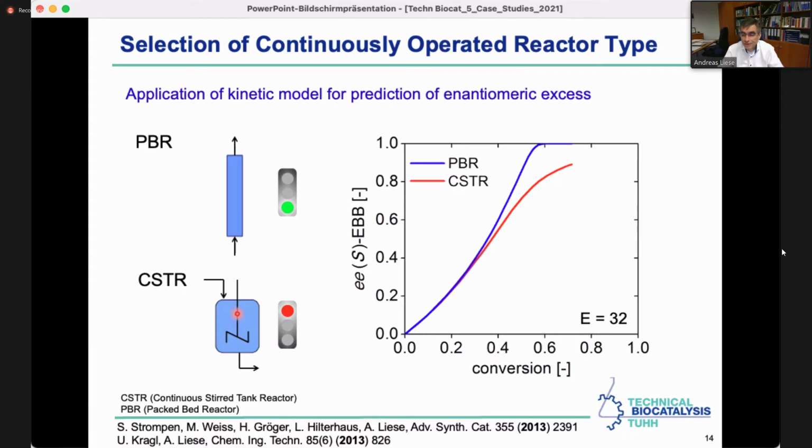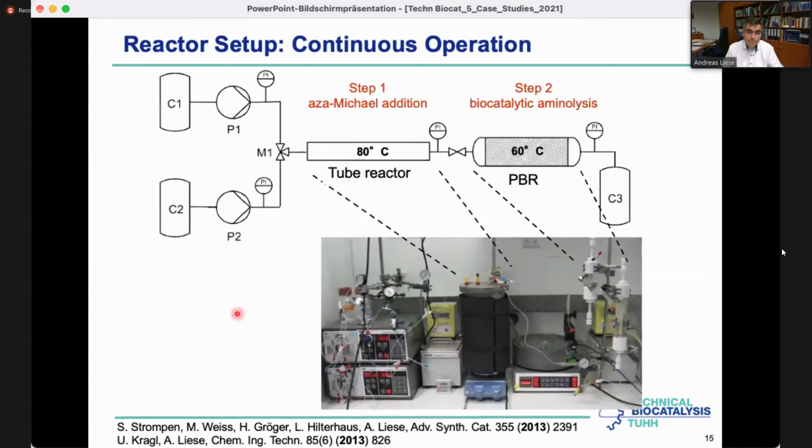And therefore the outcome of the CSTR kinetic resolution is bad. So the learning point, just a repetition from the lecture, is that if you run a classical kinetic resolution, you will normally never choose a CSTR, you will always go for a plug flow reactor. Detailed explanation and transparency seen in the respective Biocatalysis enzyme technology lecture.